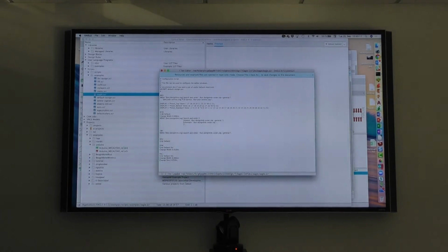If I then change the grid settings, do some work, close down, and start it up again next day, will the changes that I made be remembered? Normally, usually you're working with a project. So I create a project and have a project file. If I start a new schematic or a new board, I get the settings from the Eagle script file.